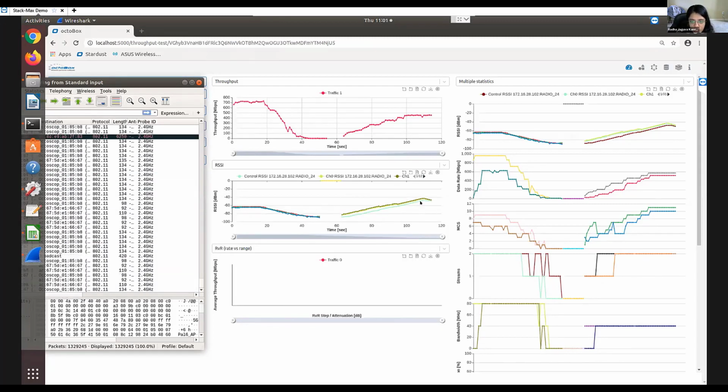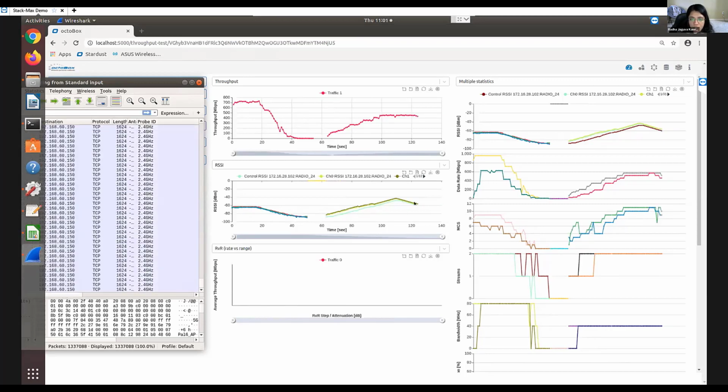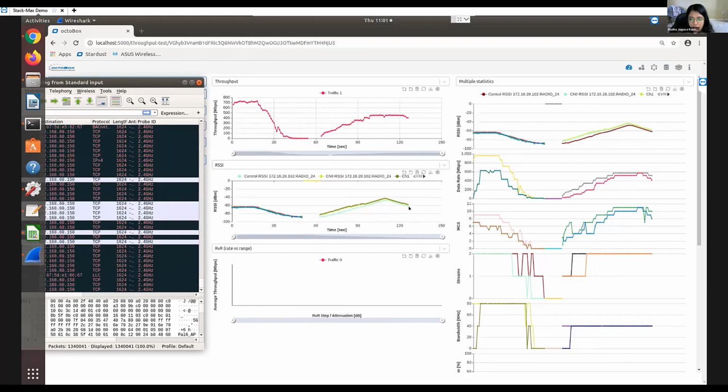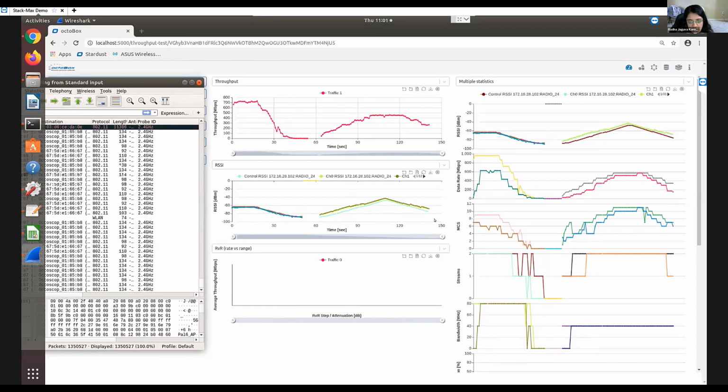We can look at all of that over the software. So I see it's a peak point, and now I see RSSI is dropping. So I know the attenuators are ramping back. We're increasing attenuation, and we're moving the client further away from 2.4 and closer to the 5 gigahertz access point. So let's wait while it's ramping the attenuators. It's going down slowly, and it's going to go up to like -90 dB for disassociation, and then scan for the 5 gigahertz access point and associate back to it.